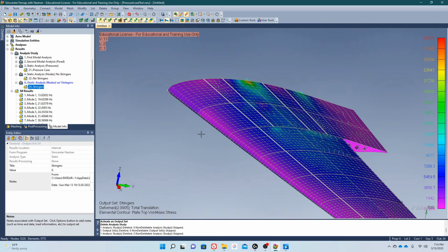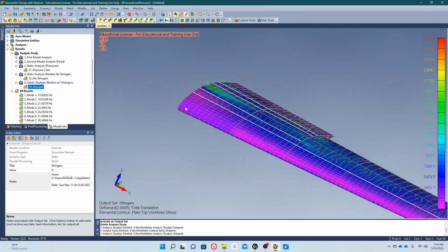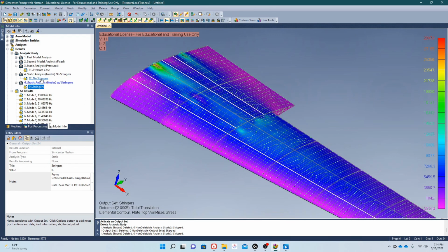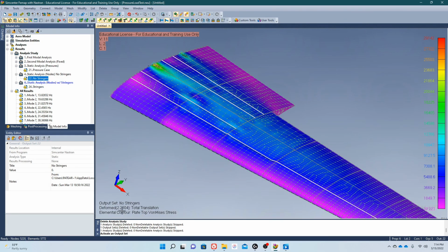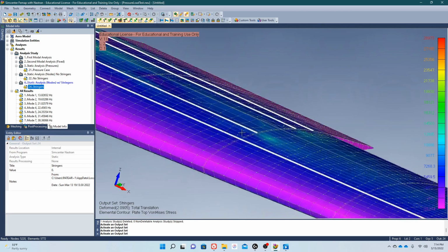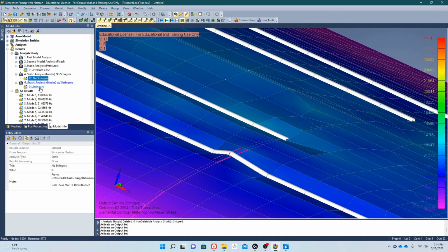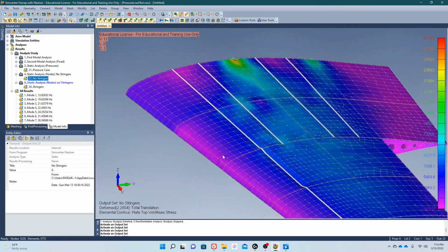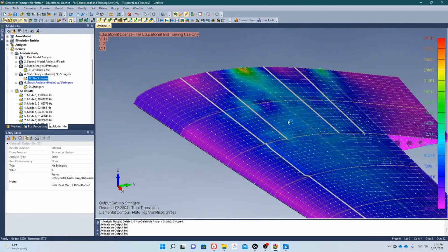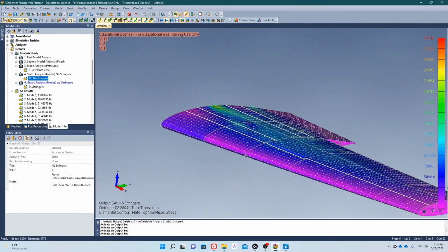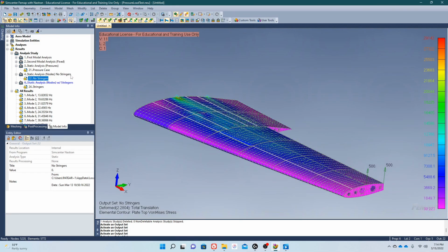Now when we look at our deformation and our stress buildup in our structure, we can see that by 0.2 inches, there's difference because of the rods. You can see how the rods are attached in one and on the other based on this deformation. So the stress buildup starts to concentrate around these rods, but it does make the structure just a little bit stiffer.